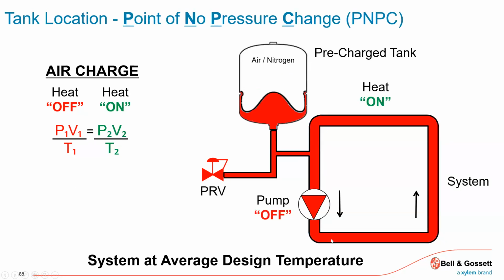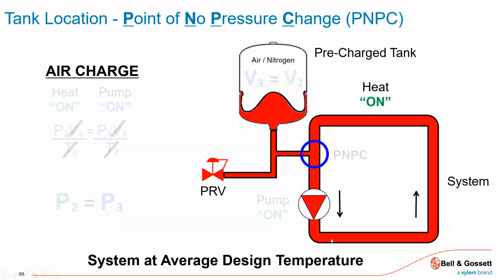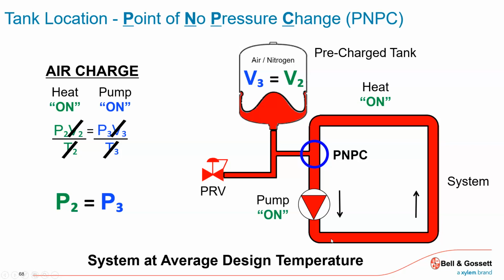Now, the pump is off and I heat the water. What's going to happen? There's going to be a change in pressure in the tank, because I squeezed the air because I've displaced it with some volume of water. So technically that connection right here, that pressure does change, but it changes because of thermal, because I've heated the water and it expands. Pump is off. Turn the pump on, and I still haven't changed the volume of water in the system. That volume change was a function of the boiler turning on, heating the water. But simply turning a pump on doesn't change the volume. So that reference point, that point of no pressure change, is very important.